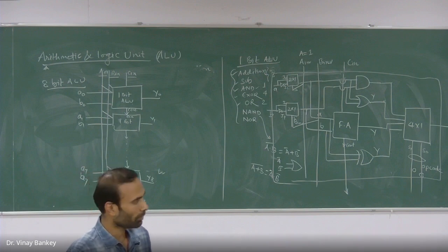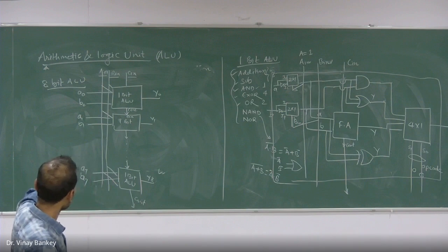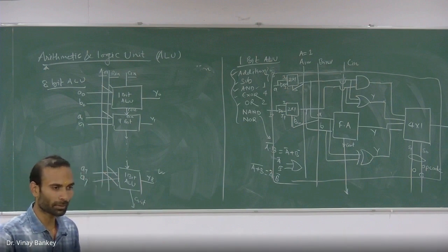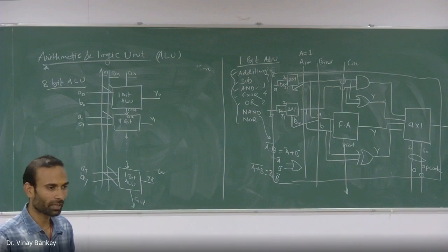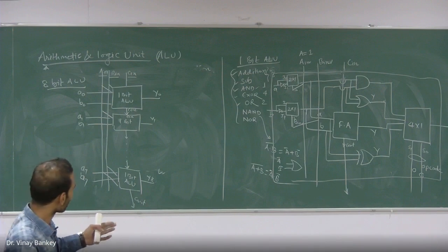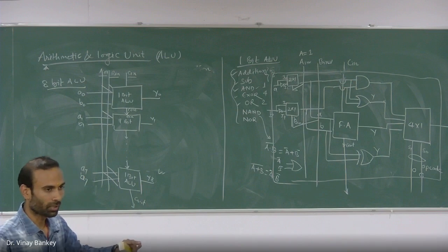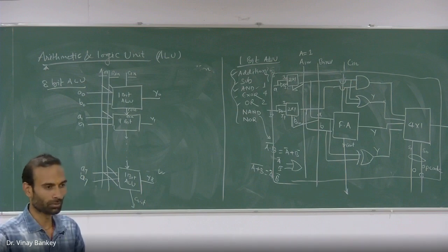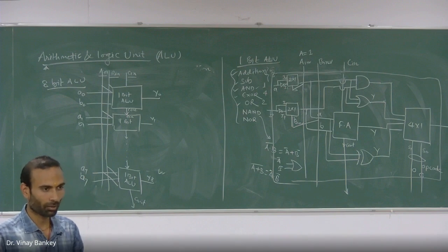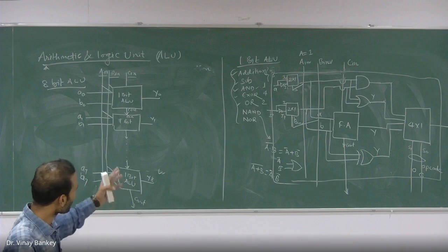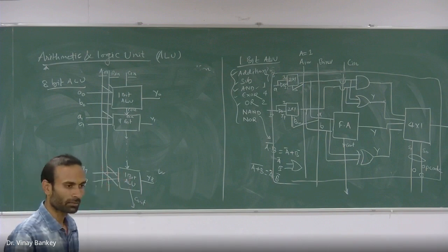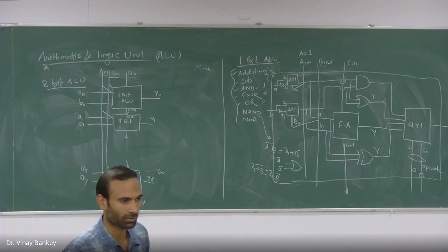No, no, it will be compulsory, because now you are performing the operation with 8 bits. So there will definitely be 8 bits. And each time you want some bitwise operation, say you want OR of 8 bits and 8 bits, you will perform the bitwise operation for each and every bit. So all these 8 ALUs will be working for each operation.